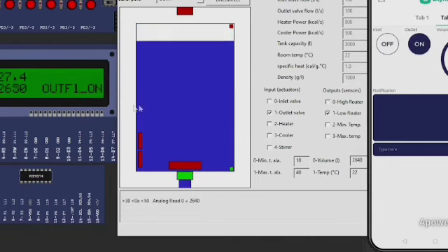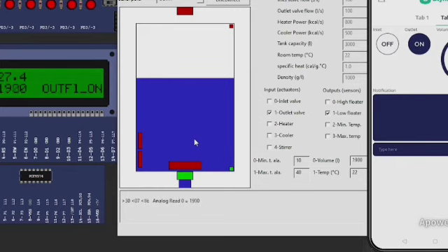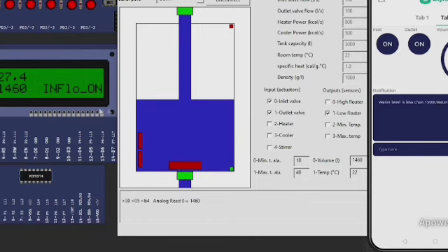The cutoff we have taken in this is 1500 actually. That is what we have changed in our code. Whenever it reaches below 1500, the inlet should turn on. As we can see, the inlet is turned on now, and a notification has popped up here saying that the water level is less than 1500 and the inlet has turned on. Now I cannot turn off the inlet because it has already reached the cutoff. Now if I turn off the outlet, the level should increase again.